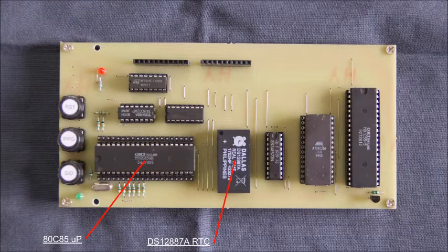The next IC is the Maxim Integrated DS12887A, which is the RTC used in this project. This RTC comes in an eDIP package with a built-in battery and crystal. It also has an internal RAM of 128 bytes, which can be used for non-volatile storage of variables or